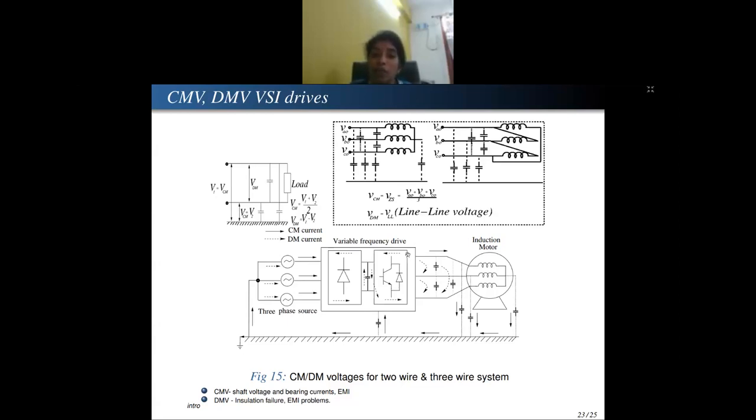Both common mode and differential mode currents will contribute to the electromagnetic interference, but the common mode currents will pollute the ground. So it would affect its own system and all others. In our house, everything is connected to a common ground, so every possible ground current will circulate through all the systems, and it would invariably affect everything. Right? Yes. So differential mode, you could say, gives a problem in terms of radiation, because it doesn't conduct or pollute from one point to the other except flowing between the lines.